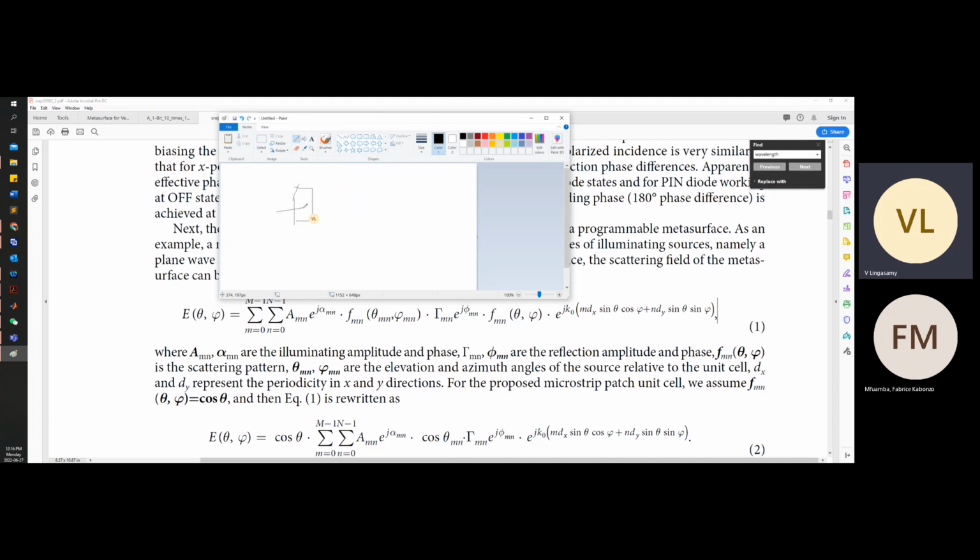If it is some standard substrate, it can be a dielectric constant of 2.2 or whatever it may be. If you want to control the dielectric constant of the substrate, you can print some metallic structure on it, for example a cross dipole or anything. Therefore, you can control the effective dielectric constant of this medium, so that you can control the propagation of waves, basically. Epsilon r.